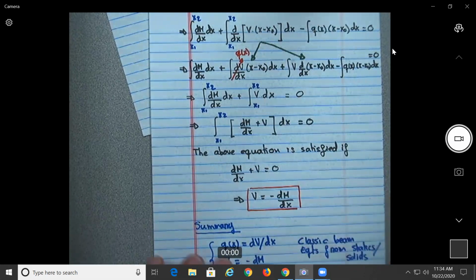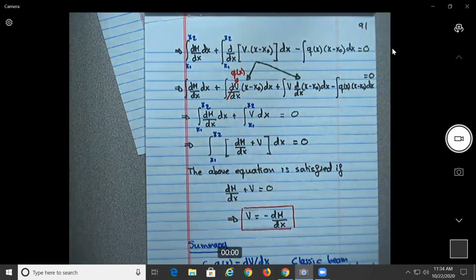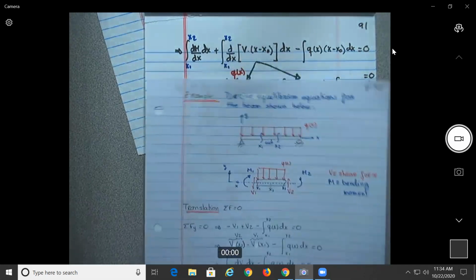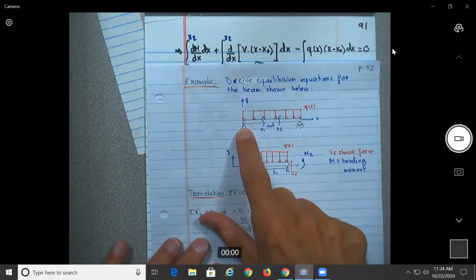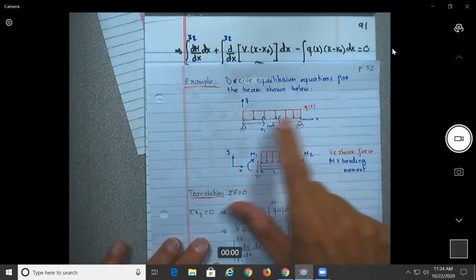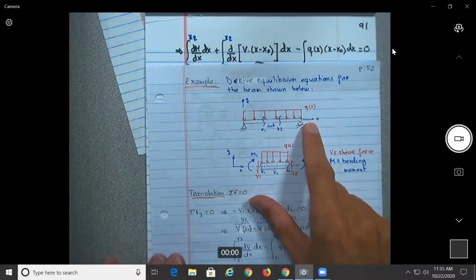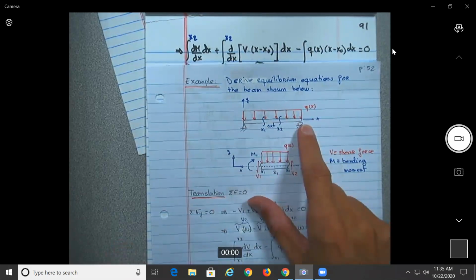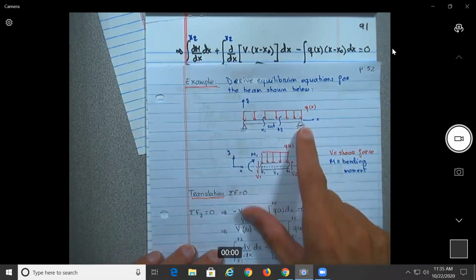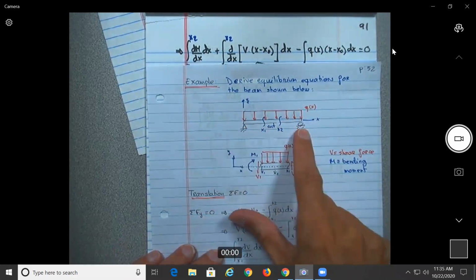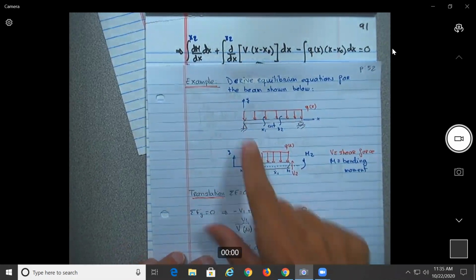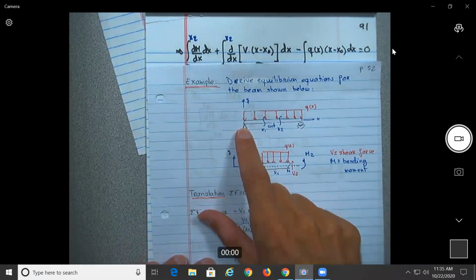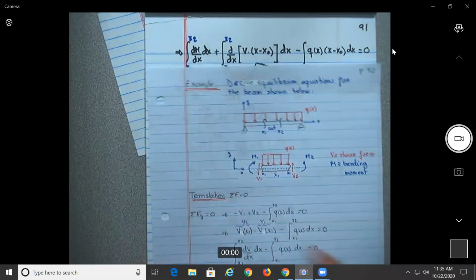Yeah, so we're not going to do it, but what would be the boundary condition that you could use over here, for example, if you needed to solve for the moment? What would be the deformation at this point? The vertical deformation is 0. You could use those two conditions, or you could use what? What would be the moments at A and B? At the two ends, what would be the moment? Moments would be 0 because it's free to rotate, no? But if it was clamped, then it's not 0 anymore. Yeah? Okay.